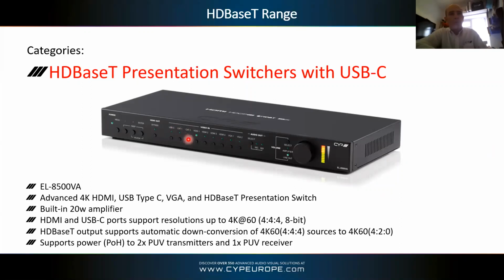So in an environment where you don't want to go through some sort of controller, or you don't want to press an input cycle button that takes ages to get through, you can do that, and there's the volume potentiometer. There we go. There's a balanced line output. Obviously, you get audio out of the HDMI or HDBaseT output, and then you've got the amplifier volume as well. You can flick through these and then just use the potentiometer to change the volume. Exactly. Again, just easy and hands-on, isn't it? It's easy for anyone to use, which is great.